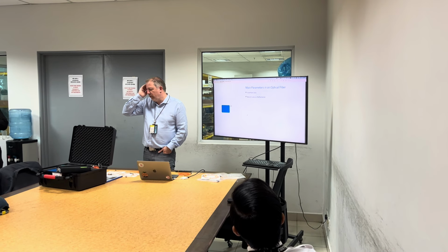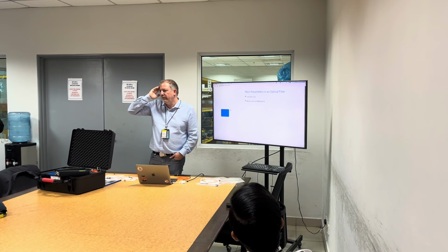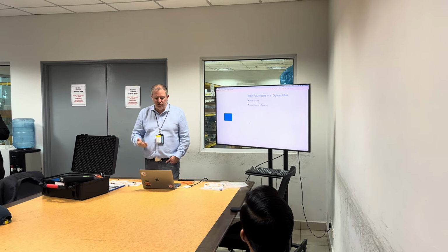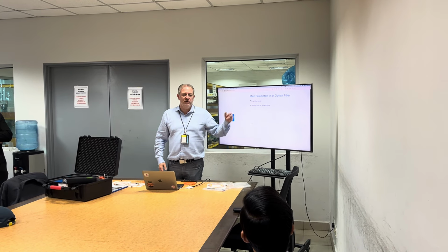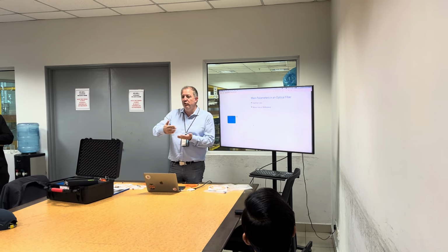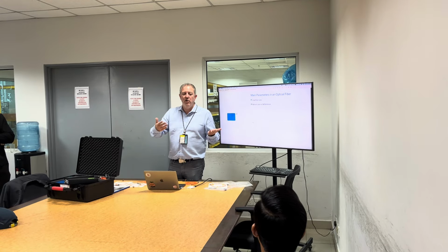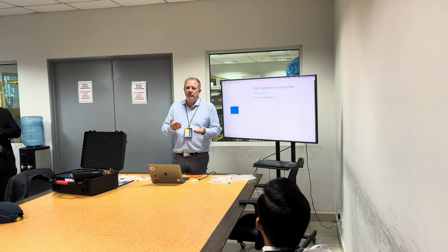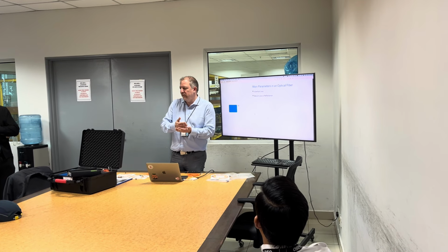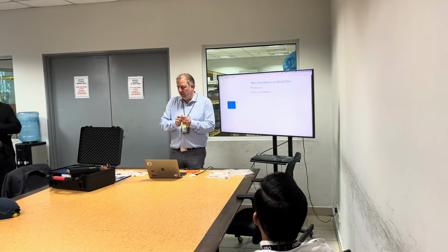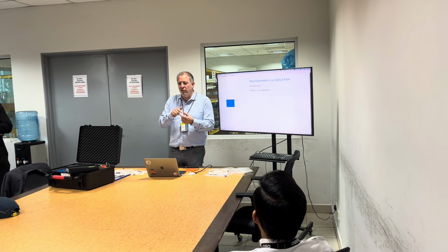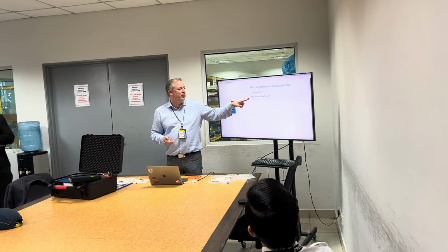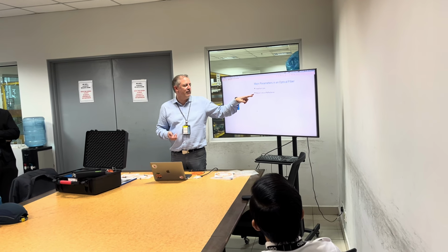So what we are going to look at is the performance of a connector, which is often given according to two parameters: insertion loss, basically the power you lose when you go through a connector, or when you go through a fault. So sometimes the connector is the issue itself, but sometimes if you have an improper bending radius, you can have a local loss of light. So this is insertion loss, and you can also look at return loss or reflectance.